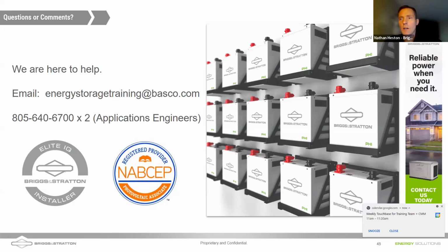So it's just under 2.5 feet wide and 7 inches deep. It's pretty compact. We've certainly packed the cells in there nice and tight, and it's a powerhouse. Like I said, 14 kilowatts out of one of those stacks. We see a lot of installations with dual stacks as well. Keep in mind, you need to install them 36 inches apart.